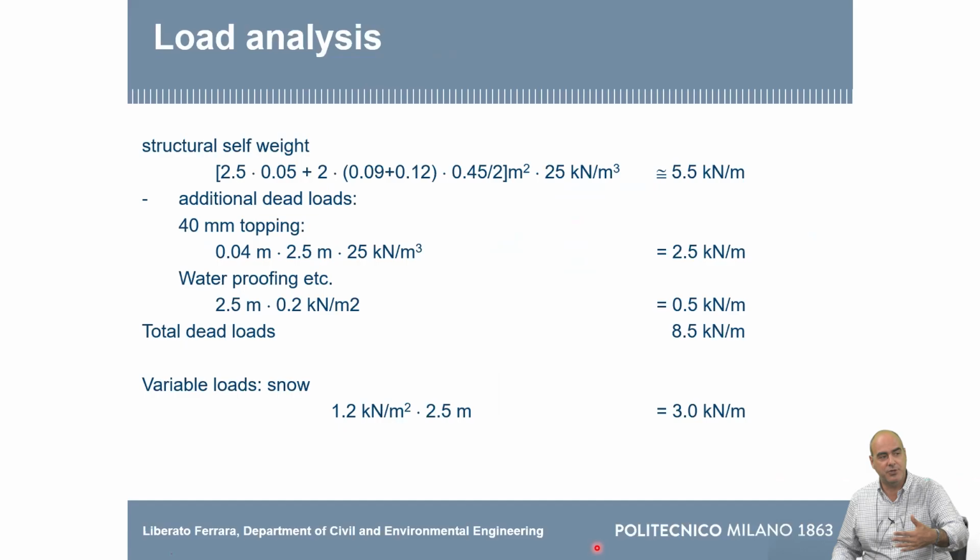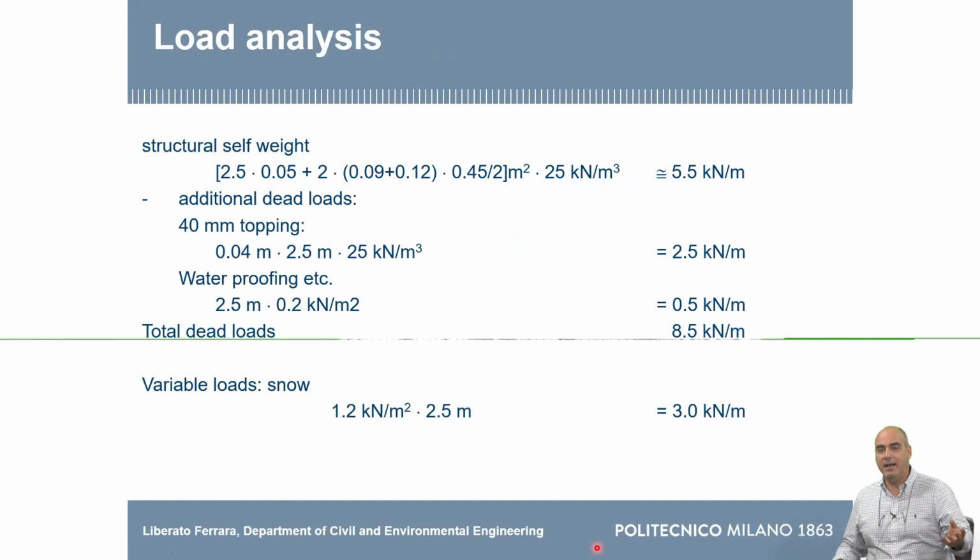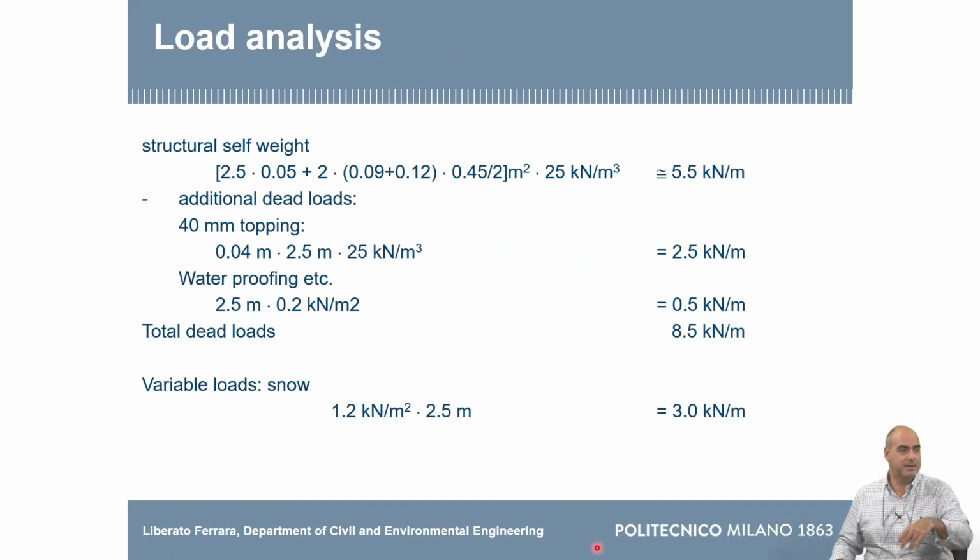This is also the structure that you will ask for in a design report. If you are certified, for example, as an engineer, you might be asked to make a final check on something which has been built, and you make some load tests there, but you also must have the design report. The design report must have this structure: description of the problem, materials, load analysis. Do not trust the design reports which come in a huge bulk of paper full of numbers or pictures in colors from a computer software.